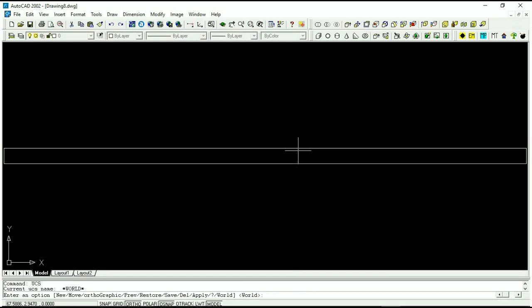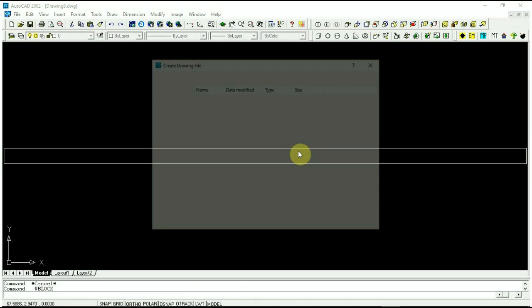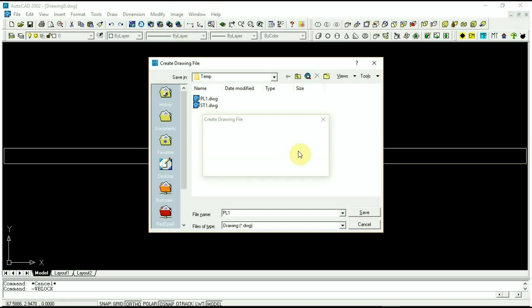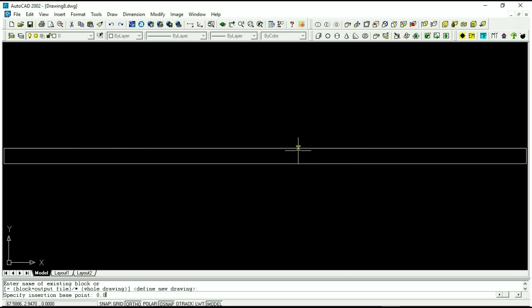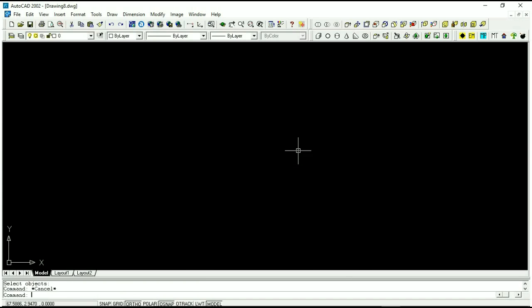And the thing I do mainly, if I type in X, it defaults to 90 degrees. If I do Y, it defaults to Y90. So typically what I do when I'm making parts is I'm just rotating about the X. And then if I want to see it, I'll rotate it around the Y if I want an isometric. I'm going to W block that out. I'm going to call it PL1. I want to overwrite the one that's in there. And there it is.